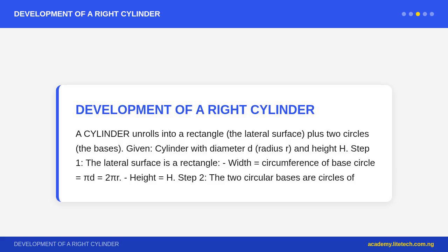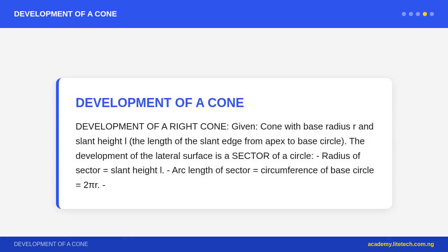Question 2. A rectangular box has dimensions 80 mm times 50 mm times 40 mm. Calculate the total width of the 4 side faces when laid flat for the development. Answer. Total width equals the perimeter of the rectangular base, equals 2 times (80 plus 50), equal to 2 times 130, equals 260 mm. The 4 side faces form a strip 260 mm wide and 40 mm tall.